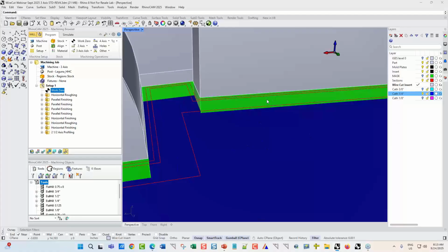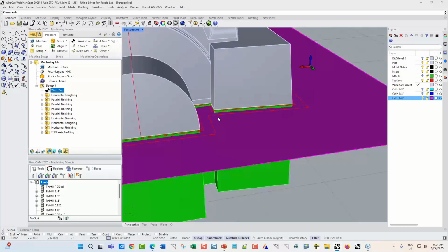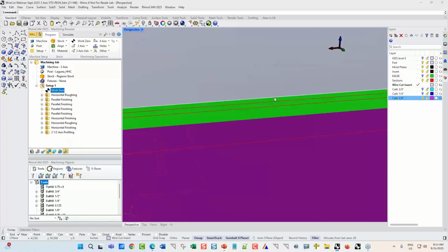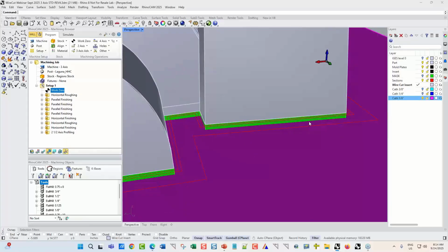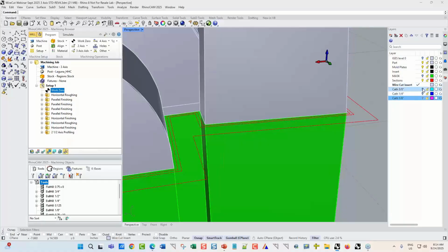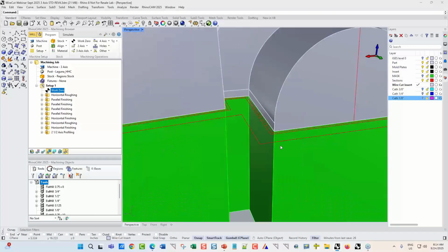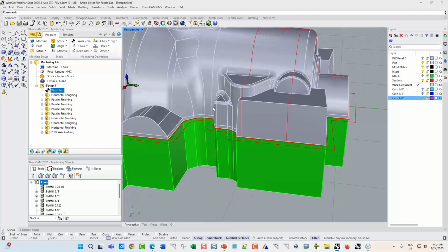So we've got a 1/4 inch, which is 1/4 inch below the parting plane. This one is for the 1/2 inch ball mill, and then we have another one for a 1/4 inch ball mill. So they're just at different levels, which keeps the ball mills tangent to the parting plane. Now, if you're wire cutting out more than one, which is actually what will happen, you can just ignore this method and just machine down, say, a 1/2 inch below this, like in a horizontal finishing operation, to match this profile, and it'll give you a nice sharp edge right there.